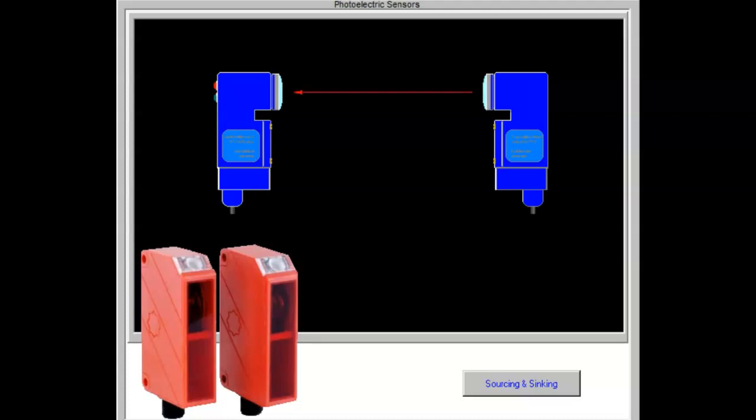An alternative is to fit the photoreceiver lens with an aperture similar to that found on a camera. This aperture will reduce the lens diameter. Direct scan does not rely on the reflectiveness of an object or that of a permanent reflector, so no light is lost at the photoreceiver. For this reason, direct scan allows you to scan farther than reflective scanning.